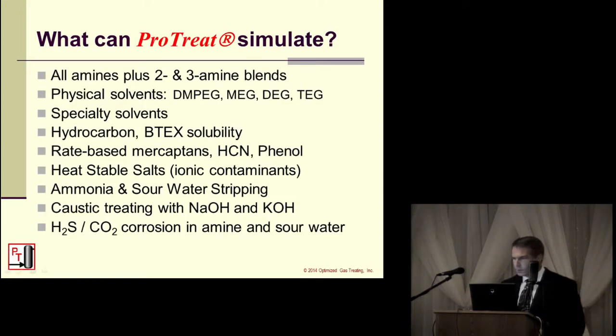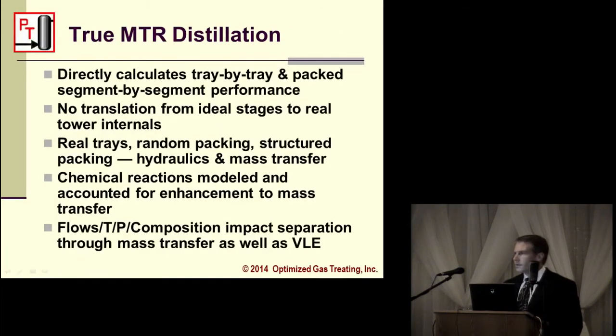And most recently, with version 5.3 that came out, we have a corrosion coupon unit operation block that attaches to streams and monitors the corrosion due to H2S and CO2 in your solution as you run your simulator. So that's all I really want to say about ProTreat.